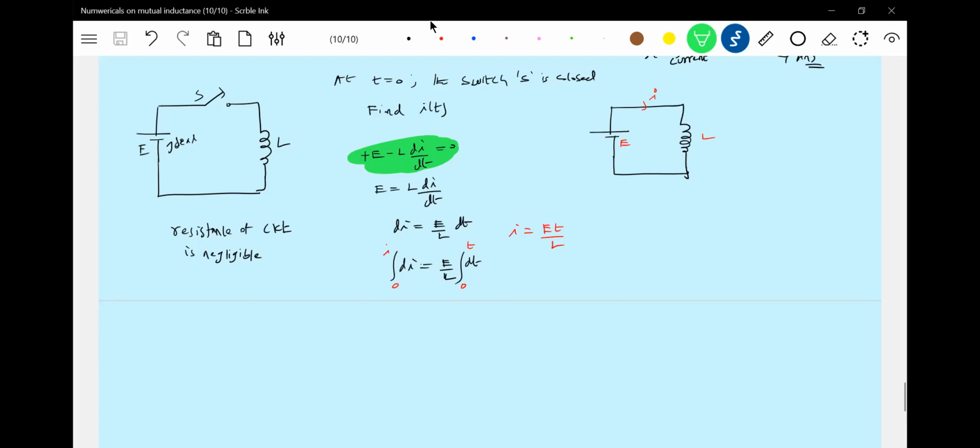Let's stick to that KVL. When we started self-inductance, I took help of KVL. For mutual inductance also, I asked you to take help of KVL. What is the mutual inductance? Due to mutual inductance, a source will be generated in a circuit. So give the polarity for that source and carry on with the problem as usual with KVL. So I think you should be ready for questions of this kind.